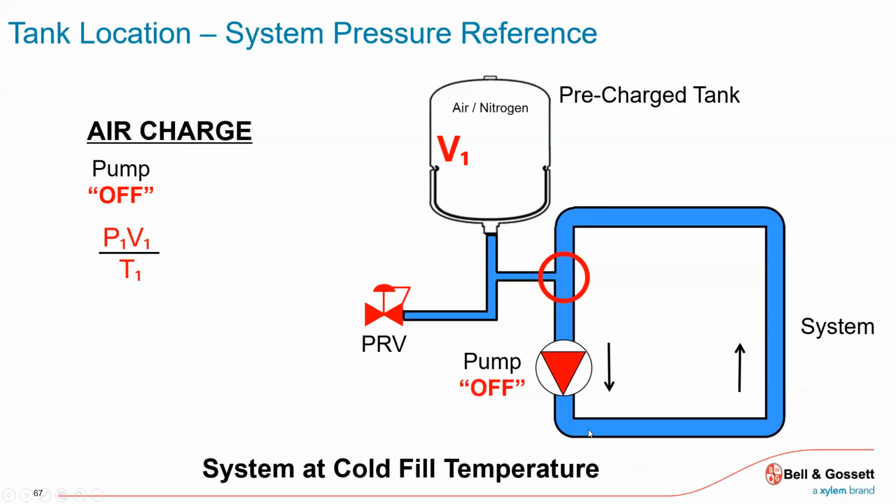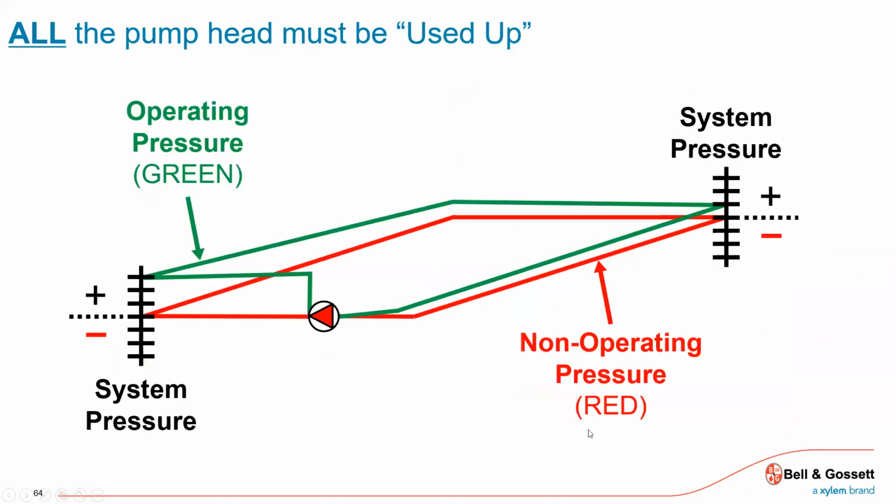Wherever an expansion tank, any expansion tank that you guys design, specify, have a mechanical contractor bid and install, where that tank connects to the system is referred to as the point of no pressure change. We always want our pumps located such that they're pumping away from that point, so that its head differential is always additive to the system.